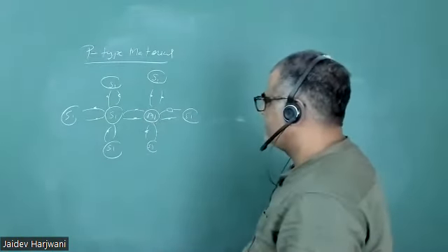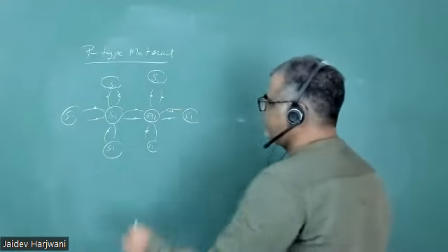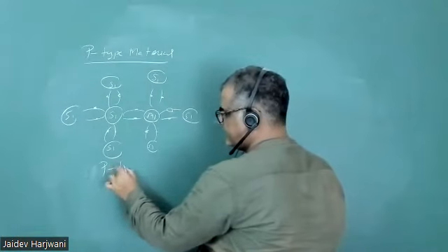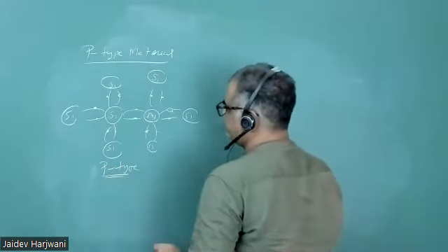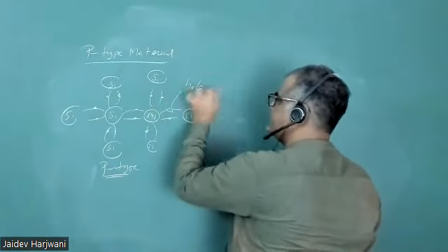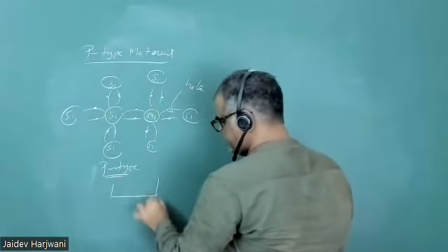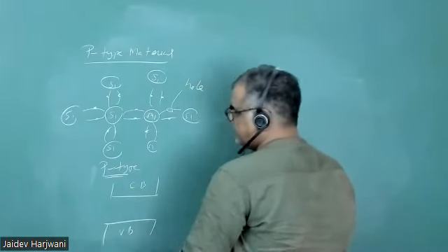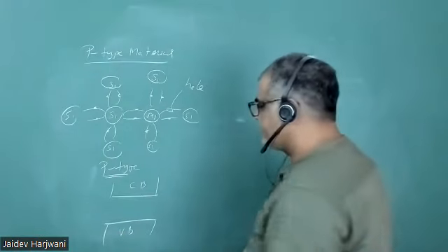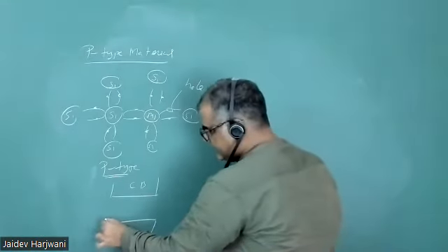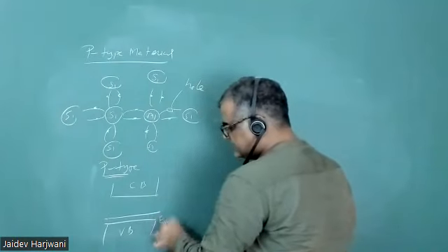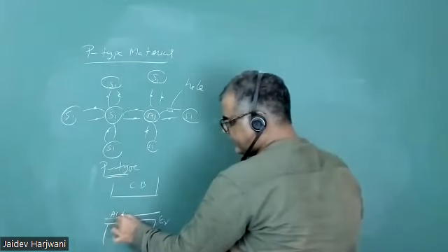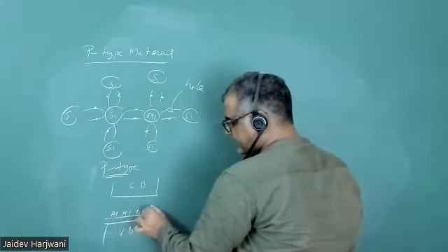Now what do you mean by hole present? Let us discuss it in the energy diagram. This is your p-type. A hole is a deficiency of electron. So now this is my semiconductor, conduction band, valence band. p-type materials are those whose energy level generally lies near the valence band, and these are the acceptor ions. So this is the aluminium, aluminium, aluminium.